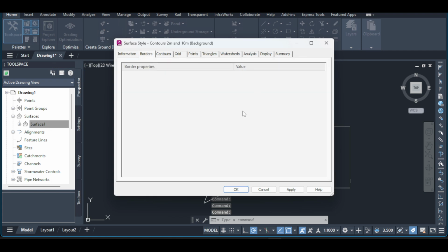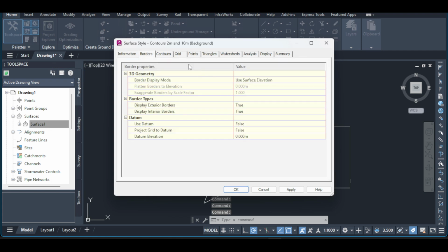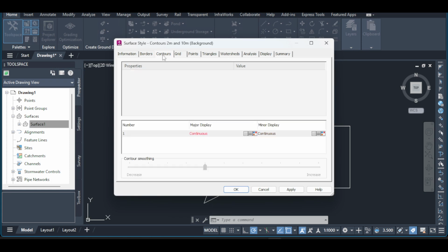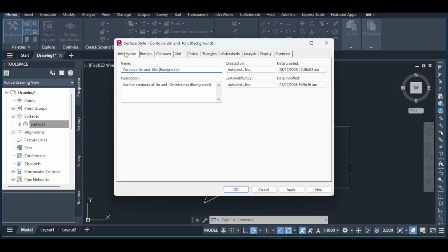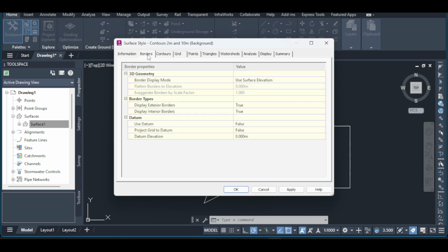Think of an outer boundary as a fence around the surface and an inner boundary as a patch that removes a hole. When prompted, select a polyline or any closed shape to define the boundary. For best results, make sure the shape is truly closed, doesn't self-intersect, and sits where you expect relative to the surface. If your boundary lines are separate segments, consider converting them to a single closed polyline before you start.